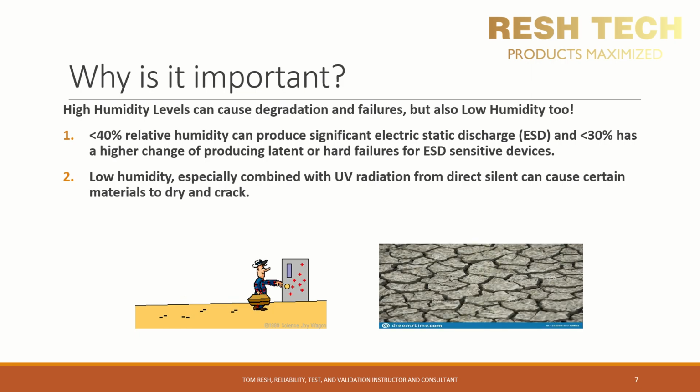The amount of potential is typically in the kilovolt range and can get as high as 100 kilovolts, depending on how few electrons are left on your skin and hair and how many electrons are stored in the negatively charged surface you make contact with. You can still have ESD events at relative humidity levels of around 40 to 60%. However, the added moisture content in the air allows charges to flow from an object to a positively charged ground through the air, reducing the discharge energy that flows between a person or object to another object as the capacitor is slowly discharged through the moisture in the air.